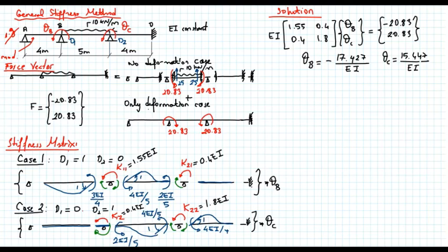So we have to recover the member end forces. There are two ways of doing that. As we discussed before, you can always use the slope deflection equations. So let's say by using slope deflection equations, let's calculate MBC.